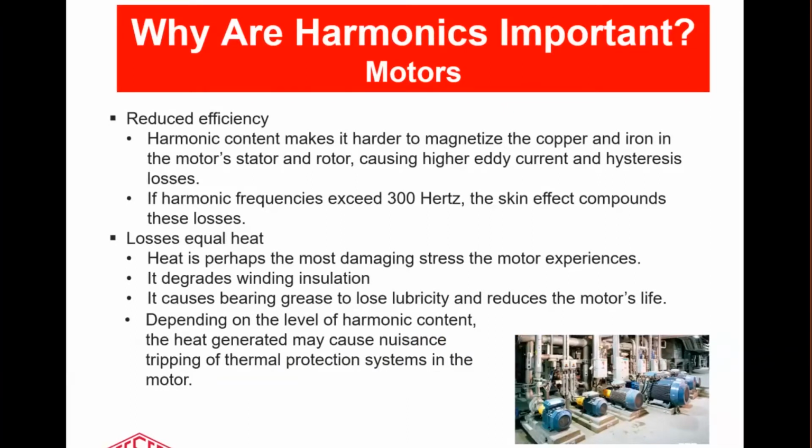If there are harmonics at particularly high frequencies, they can cause skin effects, and this reduces the actual ability of the copper in the motor to carry its rated currents. All of these losses end up as heat.